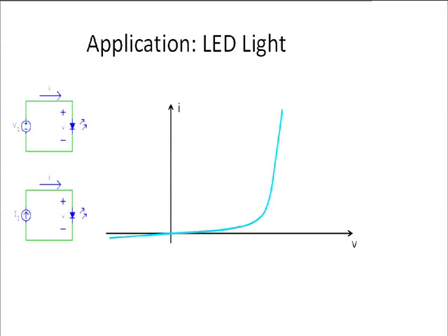So now here I've shown the characteristic of a light-emitting diode. So what happens is that if initially the voltage is 0, the current is also 0. Well, not surprising, right? How could that thing somehow generate power? Okay, so then as I increase the voltage, current starts flowing. But very, very little current, okay? And also no light comes out.